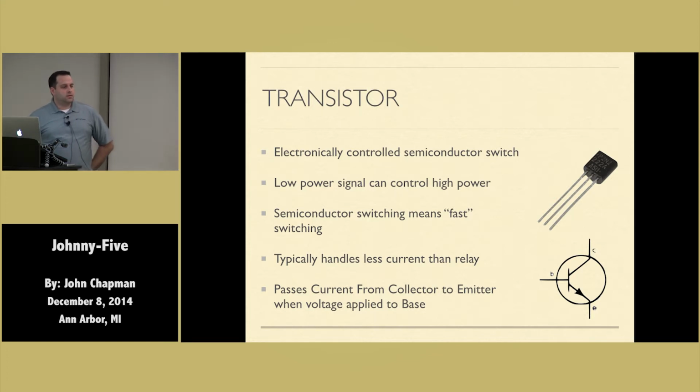Yeah, so I don't know exactly. I'm not sure if the voltage is going to matter too much. I think it'd be more about the current, which I was going to get to in a second. This particular transistor can only handle about 1 amp of current, right? But because the relay is a physical switching, you can do a lot more than that 1 amp. This particular relay, I'm not sure what the max current is that it supports, but I'm pretty sure it's over 20 amps at least on this one. But I'm sure other relays can handle much higher, right?